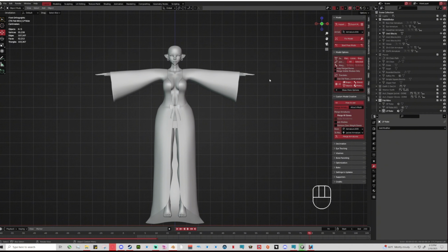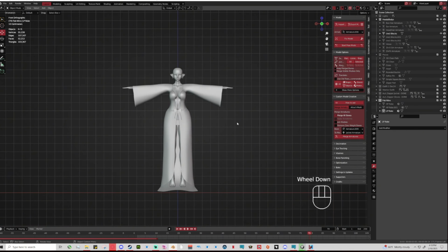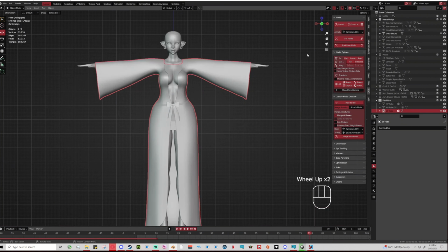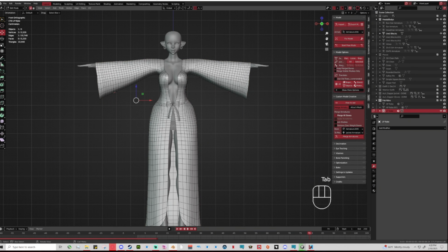I have actually noticed that if you don't have your transforms cleared, which basically sets the origin of your asset back to world origin, whenever you go to do your textures, parts of your asset will have the texture way more zoomed in than other parts, even if you're not doing that in your texturing program. So it helps make sure that everything is going to be seamless and even. So go ahead and do that before you do anything, because if you UV unwrap it and then clear your transforms, it's not going to do what we need it to do.